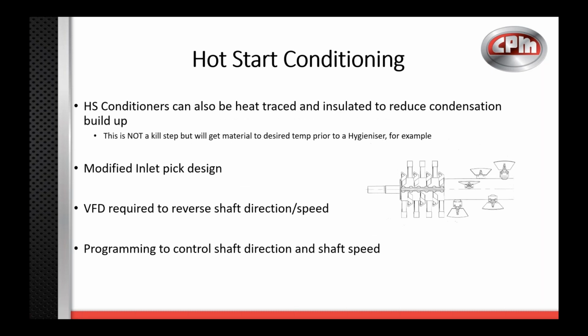So some of the things that we can do to the hot starts is we can also heat trace and insulate them. This helps reduce the condensation buildup. But I want to make this clear, that the hot start conditioner is not a kill step, because it is not a first in, first out vessel. It will get your material up to a desired temp prior to a hygienizer, for example, and the hygienizer would be your kill step. And again, we feel hygienizers are their own topic, so I'm not going to cover them today.